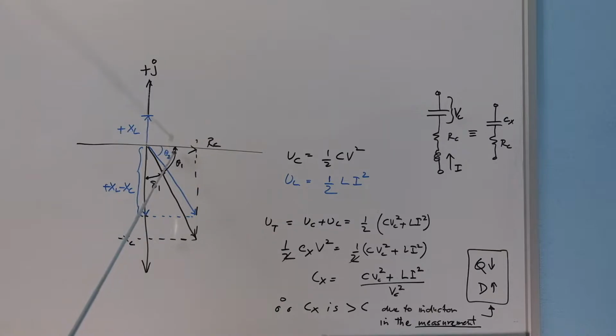Okay. Now when you add the inductor, it has a positive reactance, so that's XL, and I'm assuming it's quite a bit smaller than XC, so this capacitor is still acting like a real capacitor, and the inductor is just a parasitic element. So now because these two are exactly 180 degrees apart, you can basically subtract or add them numerically, one being positive, one being negative, so you get a slightly smaller reactance which is still negative but turns out to be XL minus XC.